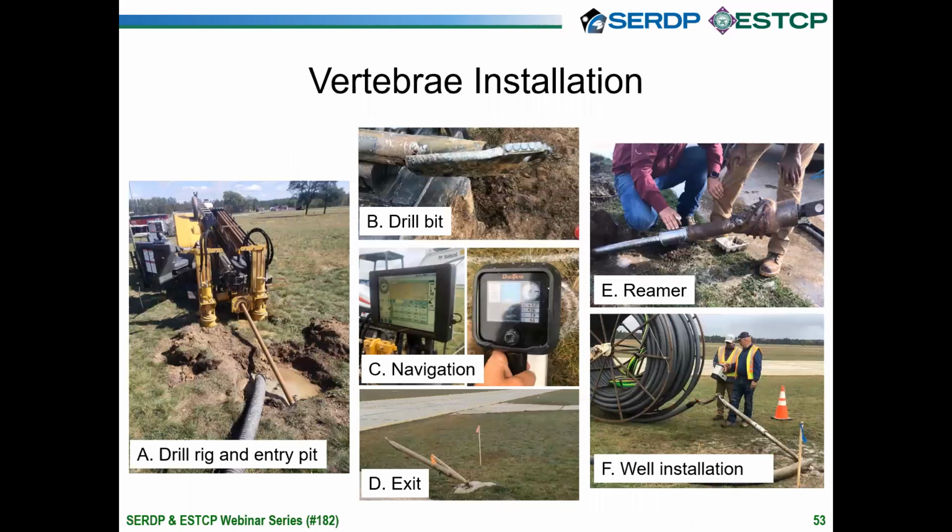As I mentioned before, the vertebrae technology has been around for several years, and so the installation methods are pretty well established. Photograph A shows the relatively small low mass drill rig and the entry pit. You can also see the mud in the pit, which is used to bring the cuttings back to the surface and keep the borehole open. Photograph B shows the asymmetric drill bit that is used to cut and steer. Photograph C highlights the real-time navigation system. A transponder is located immediately behind the bit that emits a signal which is detectable by a walkover navigation system.